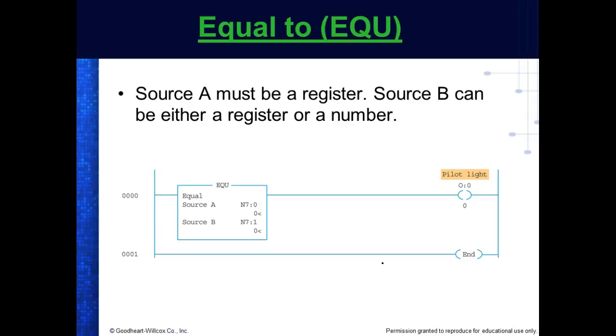The only ones we're concerned with right now are immediate and direct, and we'll get into indirect addressing later. Immediate means we have constants, right? Direct, this register contains the operand. On indirect, this register would contain an address that points to the operand. So we get the address indirectly from a register.